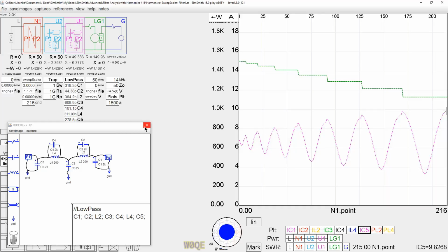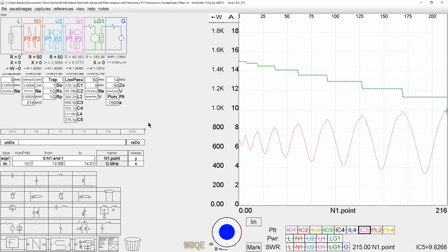So there's a lot of interesting things. By playing around, you can really glean a lot. It turns out I made a comment that I might have been just as well off to have swept this impedance right here with nothing more than a piece of transmission line attached to a 3-to-1 SWR. And from what this shows me, the answer is yes. None of these impedances back here gave me a value larger than what I saw in the biggest step.